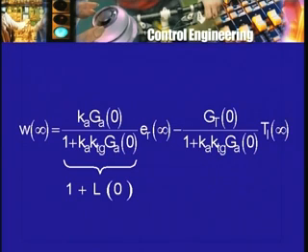So, if I know the required steady value of the speed, and under what torque condition I want that value, so I know TL infinity, and if I know the tachogenerator voltage coefficient, and Ga and Gt, which involve the parameters of the system, I can calculate, and I choose the value of Ka, the gain of the amplifier, so to speak, I can find out the reference voltage that needs to be applied to produce the correct speed.